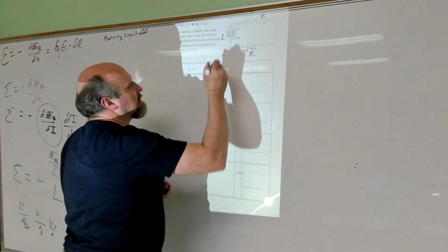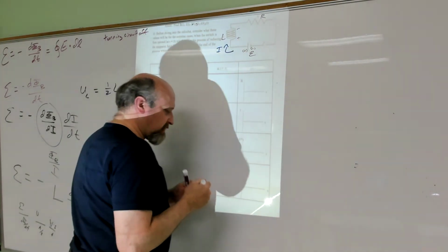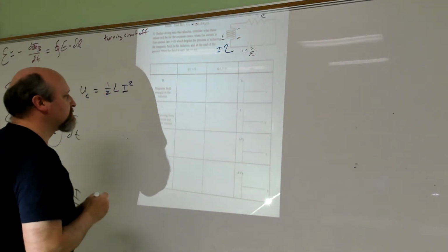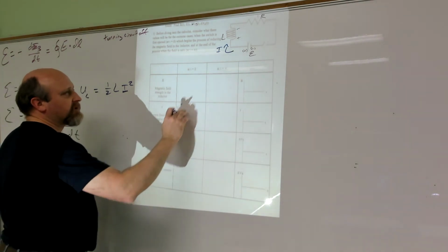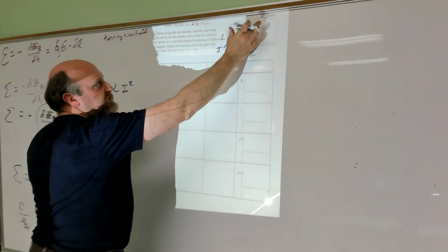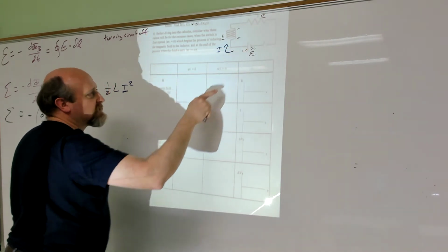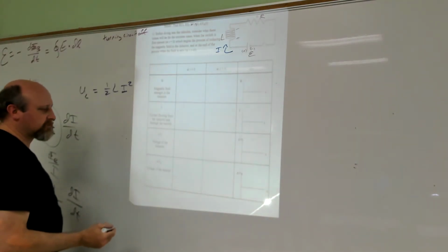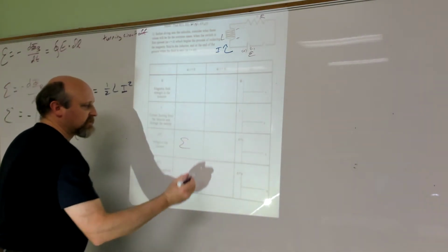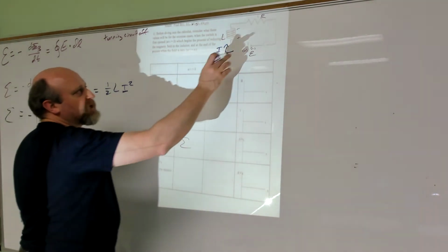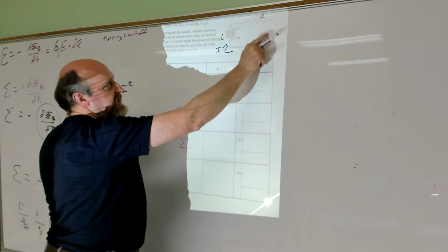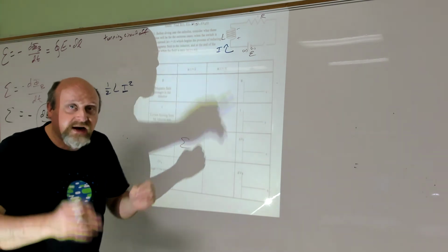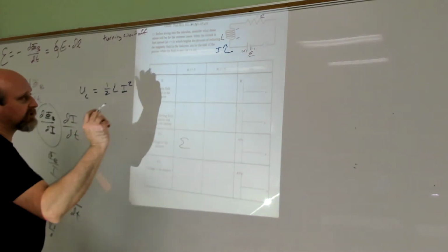It's going to keep that current flowing. It's going to act like a battery to keep pushing current through that resistor. So at the start, at time 0, whatever the delta V of the system was over that resistor before, it's going to keep maintaining that delta V to maintain that current in that branch. So at the first start, the voltage of the inductor is going to be that EMF of the battery. The voltage that this circuit was at here, it's going to try to maintain that voltage to maintain that current. That's the way to think about it. It makes it pick up from where it left off when you open the switch.